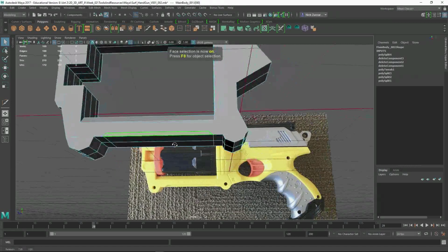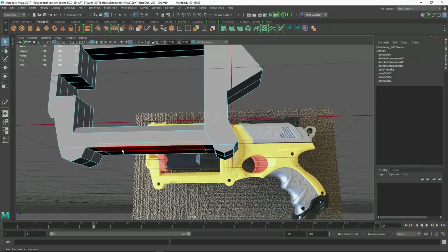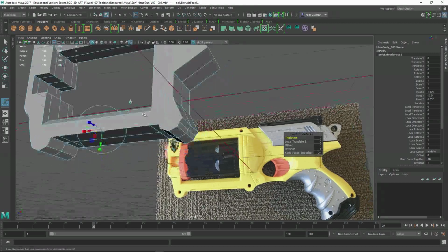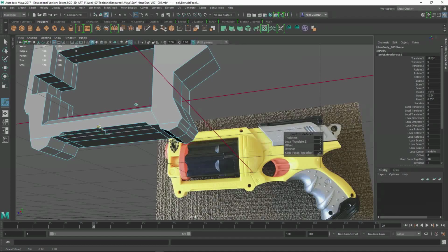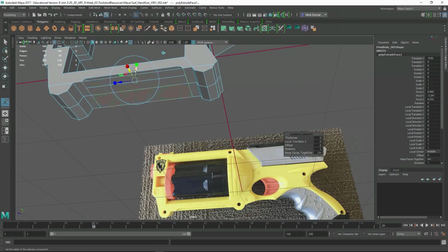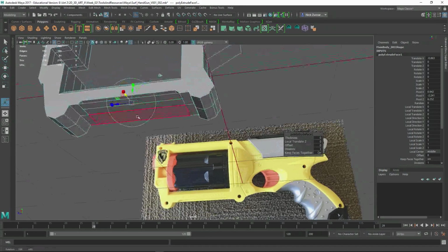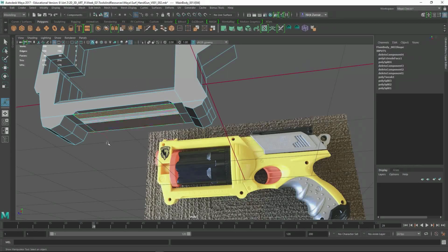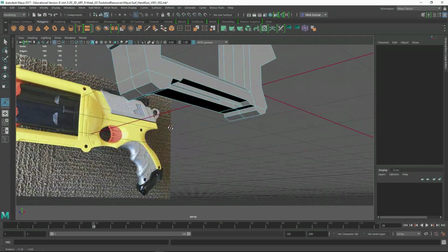So if I select this face, F11, and Shift right click on there and say extrude face, I'm going to take it off of this mode here and put it into world mode for moving back. And what I'm seeing is it kind of comes in about this far, about in through here. Now I will have to take this face and delete it and get rid of it. Going to get rid of this face as well.